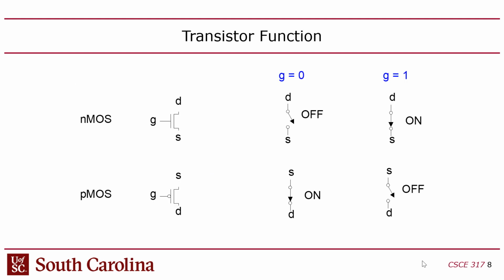This slide's from an earlier lecture when we were talking about the push-pull drivers. So with an NMOS, this is the schematic symbol. You've got the source, drain, and gate. There's actually a fourth terminal that's usually not shown. That's the substrate terminal, or the bulk terminal, or body terminal. In this case, that would be grounded, right? But that's not shown here. So when the gate is on, you connect. When the gate is off, you disconnect. Right? That makes sense, right?